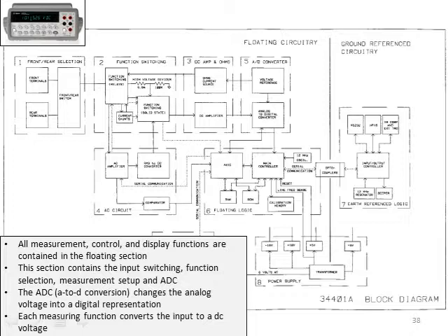The power supply for this system, you want to plug it in, but also you don't want it to be powered directly from the wall. It has an isolated power supply to run the logic within the system. And then it has a grounded reference circuitry as well to prevent floating potential due to, as we saw earlier, if you don't ground your system correctly, then you can introduce potential variations into different parts of the circuit.